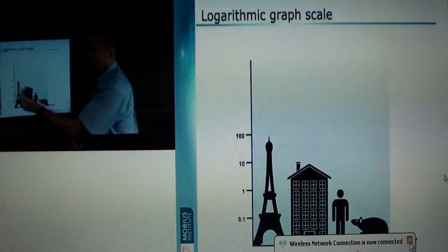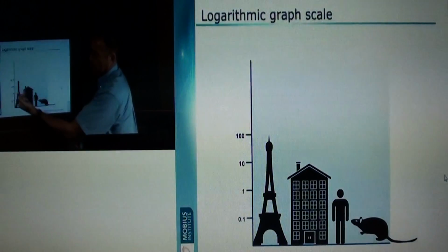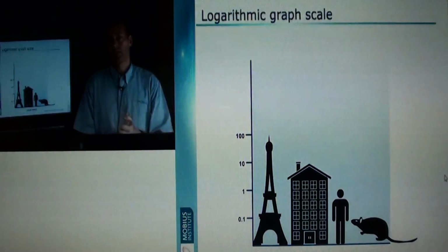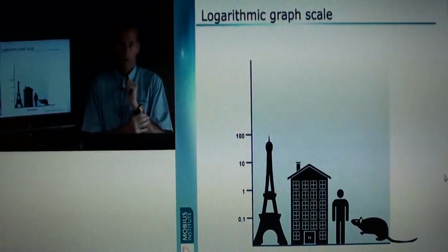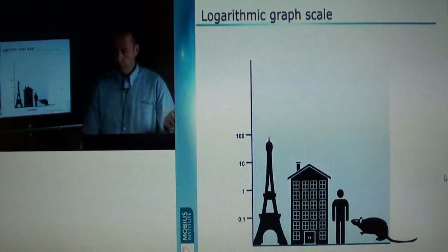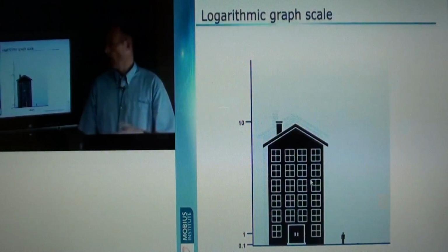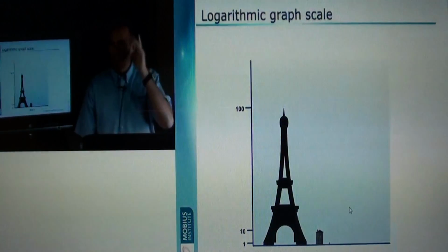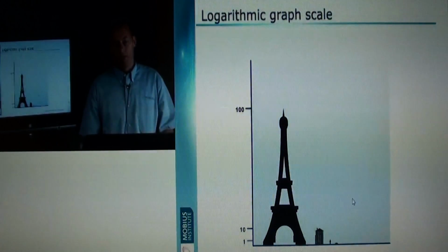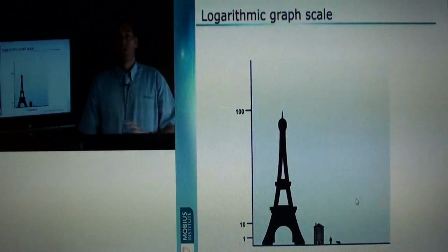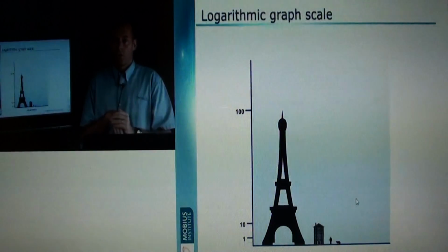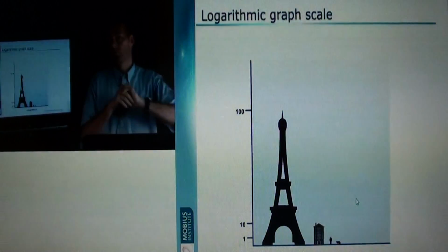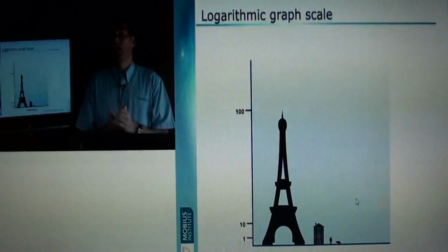No, if I saw harmonics at this frequency, this frequency, this frequency, and this frequency, I could panic and think that it's a looseness problem. Whereas no, I've got one dominant peak and a bunch of other little peaks. So you do have to recalibrate your mind a little bit, but that doesn't take long. But it's up to you whether you look at log occasionally or look at it as your normal graph of choice.